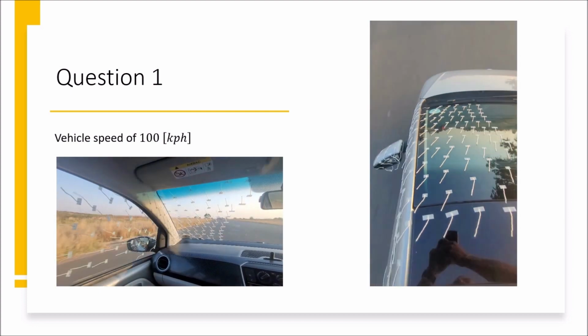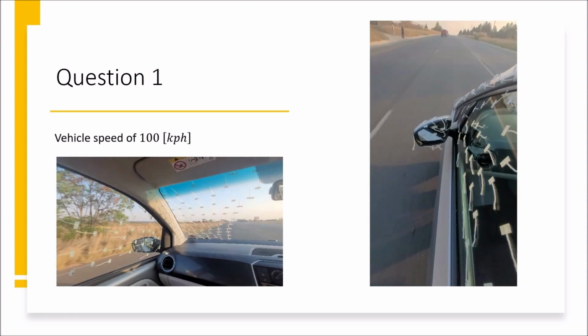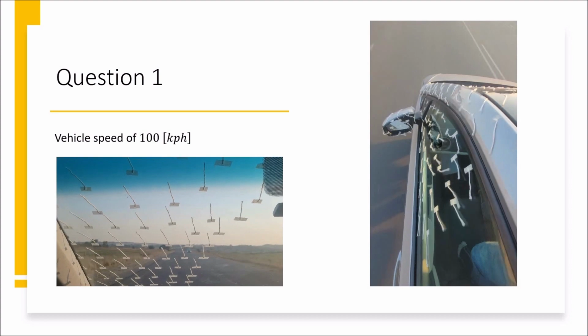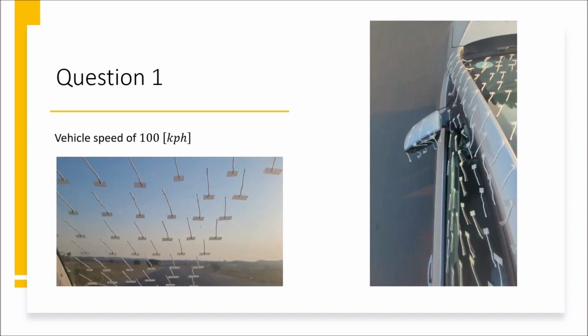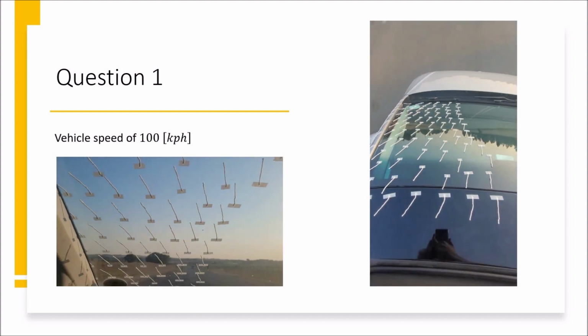The flow over the passenger side window follows the direction that the vehicle is traveling in and is relatively attached to the surface of the glass at the bottom of the window. Observing the flow nearer to the top of the window, it gets closer to the A-pillar and roofline, where there is some flow separation happening.